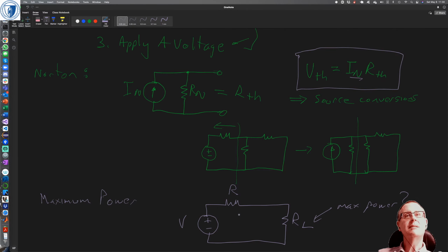You could think about this as your cable, right? And this as your set-top box. And you get better reception on your set-top box, even with digital, if the set-top box gets the most power it can, right? Because usually the thing that determines signal quality is a thing called signal to noise ratio, and the more power you have in the signal, the easier it is to poke above the noise.